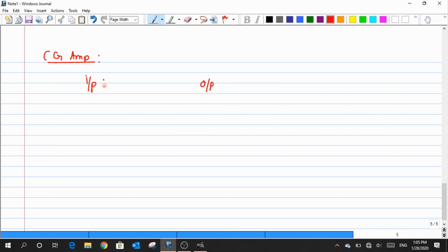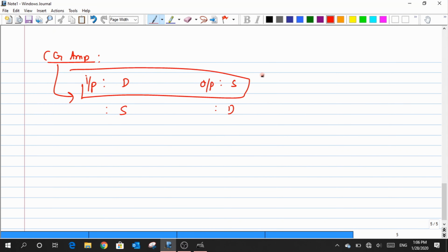The second part of your problem, the last problem, where we had a given circuit which is almost like common gate, but the point is that we had interchanged this. We had fed the input to the drain and we had taken the output from the source. Normally for a common gate, we actually have to feed the input to the source and we'll take the output from the drain. But when I do the other way, we found that the gain of the circuit falls less than 1. Okay, so which doesn't serve for any purpose.